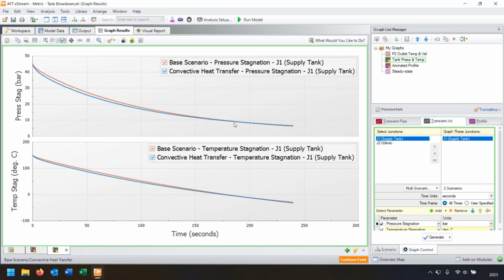Here we see the pressure in the tank is very similar. If we were looking at our 10 bar condition, again, it looks like it's within a second or 5 of itself. So good enough for us. Again, maybe those temperature effects, if we're looking at max temperature, maybe that's dramatic. If we're solely looking at the heat transfer or the depressurization of the tank, we got there in the end, so maybe adding those heat transfer effects is not as important. The hard part is we don't know until we try.